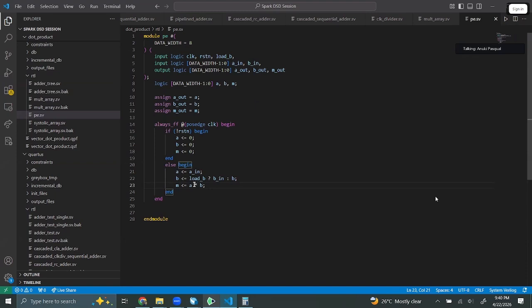But if, let's say, DSPs are limited, like we need to do more multiplications than the amount of DSPs, then some of them might be synthesized using normal LUTs. That all depends on the resource availability of the board. But to use DSPs, you don't have to do anything special unless there is a very large number of multiplications.